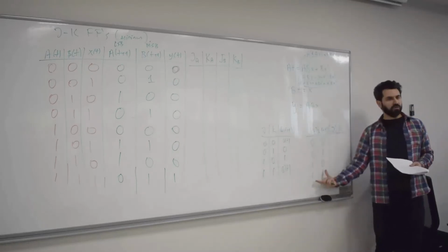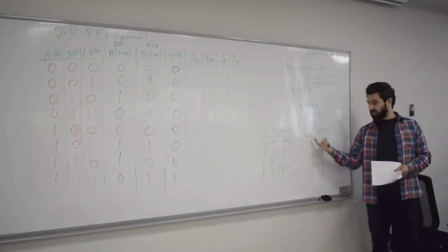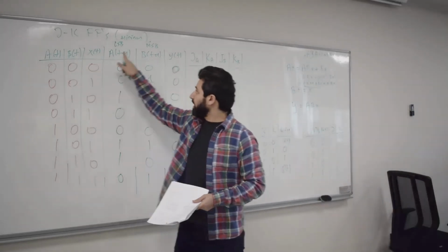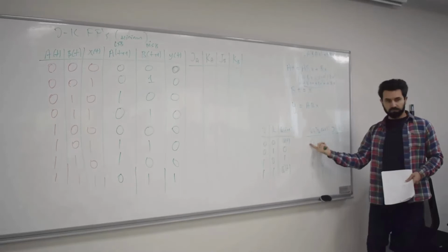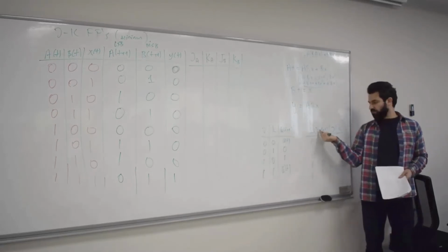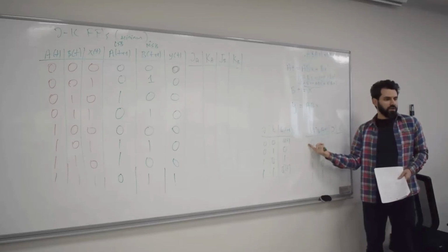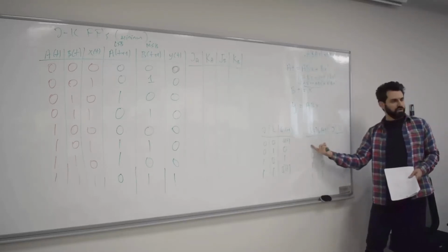These are inputs now in your table because you have access to these now, right? You see, for example, here, AT is 0, AT plus 1 is 0. That's why I have these 0, 0 here. Okay, put in place of QT, and boom, you got AT and AT plus 1. The question is, what should be J and K corresponding to these Qs?